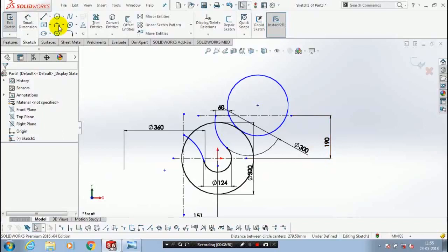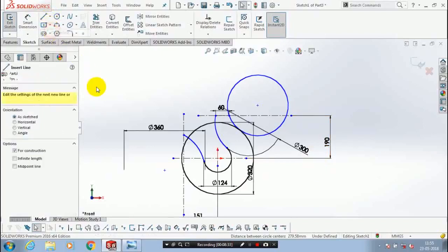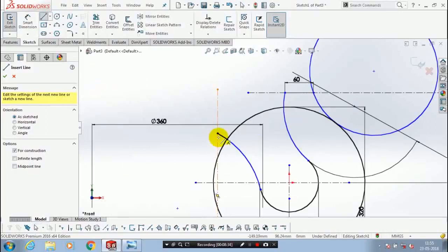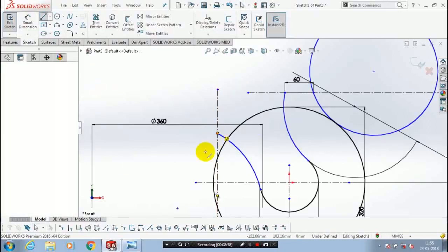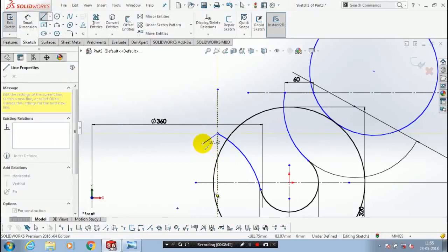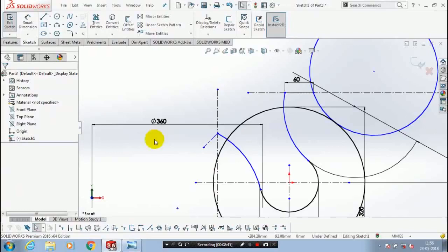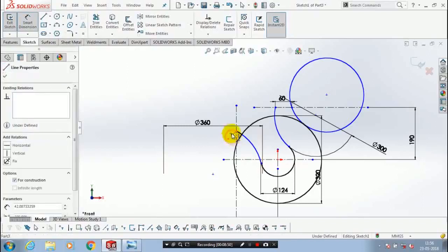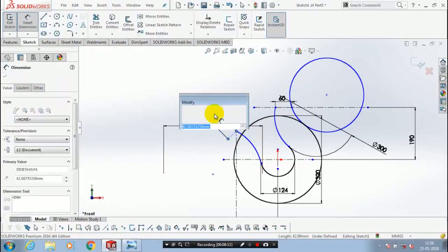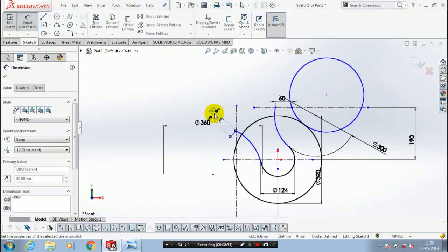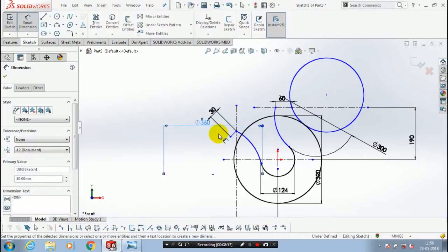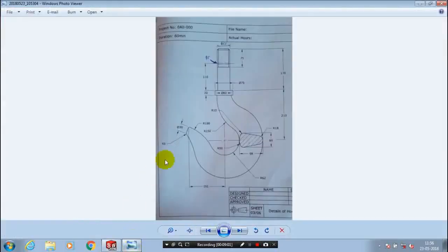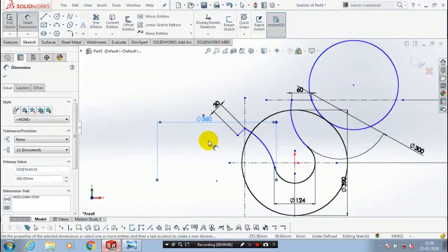After that we have to draw one more circle. Make the center line a reference. Draw a center line at the end of gate curve 1. We have to give the dimension for this center line. Give the small dimensions. We have to specify the length of the dimension as 30 mm because the end cross section is 30 mm. We have to go for reference dimensions. Here the 30 mm is the cross section, so we have to draw a center line reference for 30 mm.